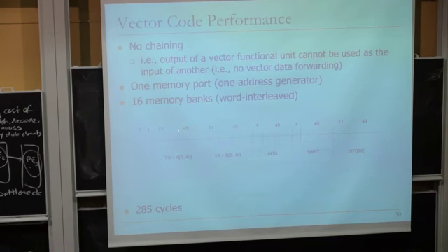We've already fetched the first element of vector 0 at the end of the 11th cycle here, and we fetched the first element of vector 1 right here. We don't need to wait for the entire vector to come to start the first addition of the first elements. So all we need to do is to supply this to the add functional unit. That way we can start the add right here. Right. Yes?